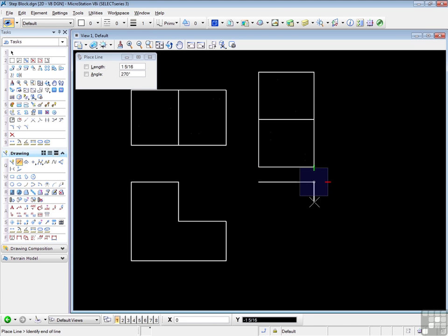And that is one of the major points, of course, about using this method, is that I can immediately reference that width information, come down, enter, pick up the bottom corner, come across, enter, pick up the top corner, and go back to my starting point.